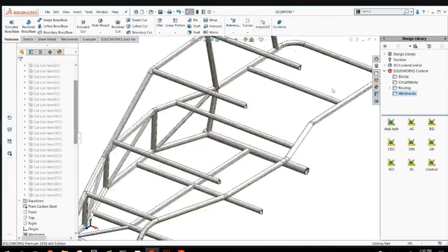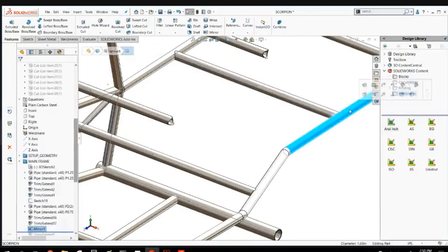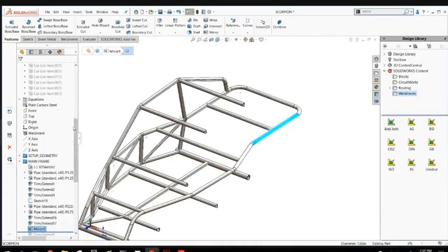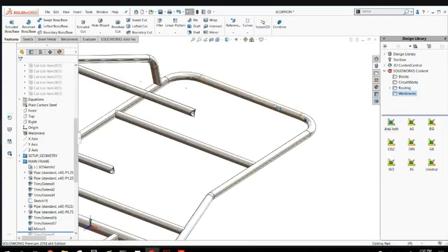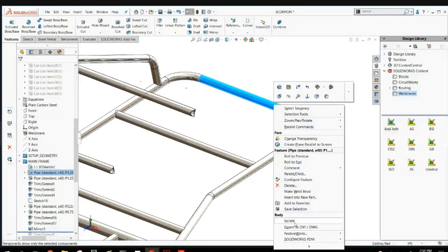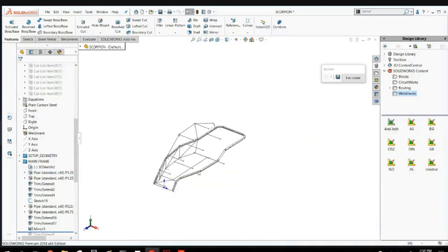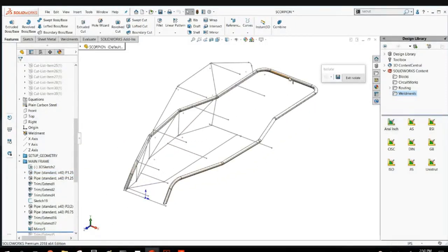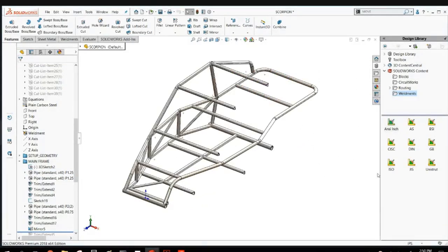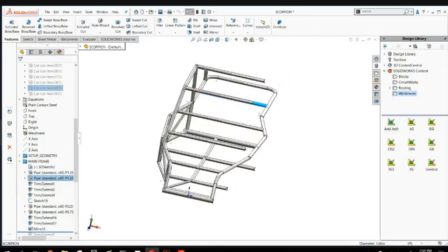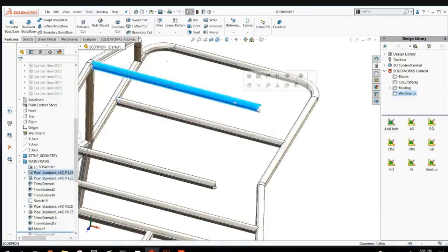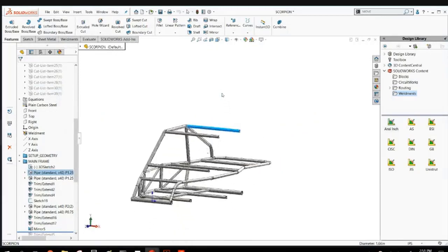But it's pretty smart about it. It didn't merge this one into this one. They stayed their own pieces, where if I isolate this one, it's not connected to all the rest of those pieces. It just merged at the point that it touched itself. So when you do the merge results, what it does is it'll give you twice as long of a pipe, basically, like this one here. It used to only go to the mid plane, but I told it to mirror, and now it's one single piece of pipe for the cut length.